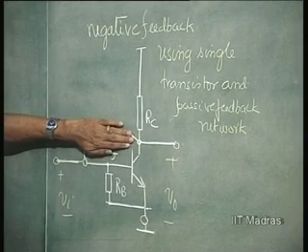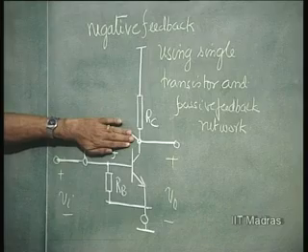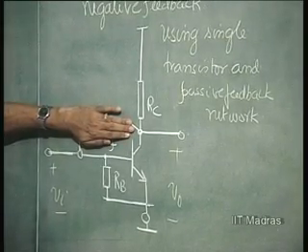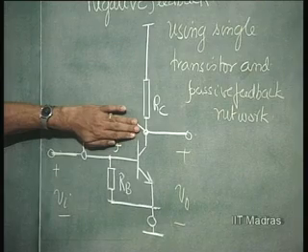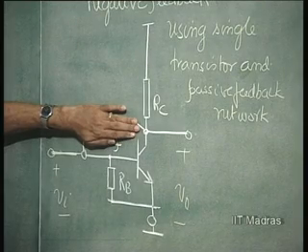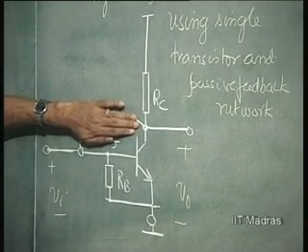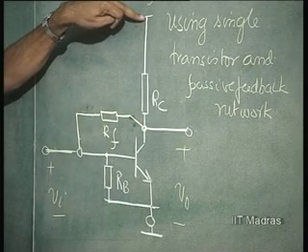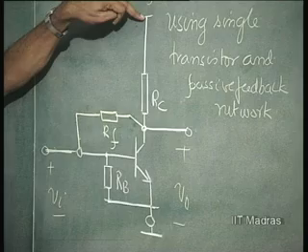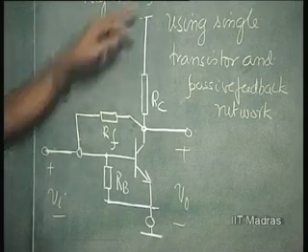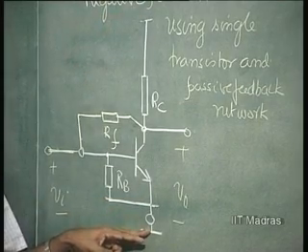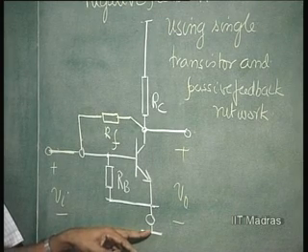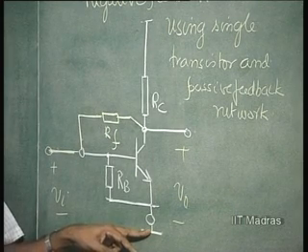Whatever has been earlier put in white chalk is the circuit necessary for biasing, okay, etc., and this is giving only the AC picture. What I mean is, I have collector resistance normally connected to the supply. So, this is connected to the ground as far as signal picture is concerned. Emitter is grounded because it is a common emitter amplifier. There might have been a resistor in the emitter which is bypassed, okay, or it might be a differential amplifier stage, whatever it be.